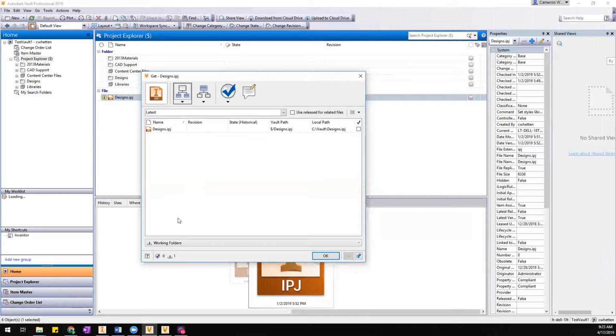It's often overlooked, and then you've got people working on old project files, which maybe put the Content Center in a different location, and you run into issues that way. So just make sure that everyone's using the same project file, and if it changes, everyone gets that change. Perfect.